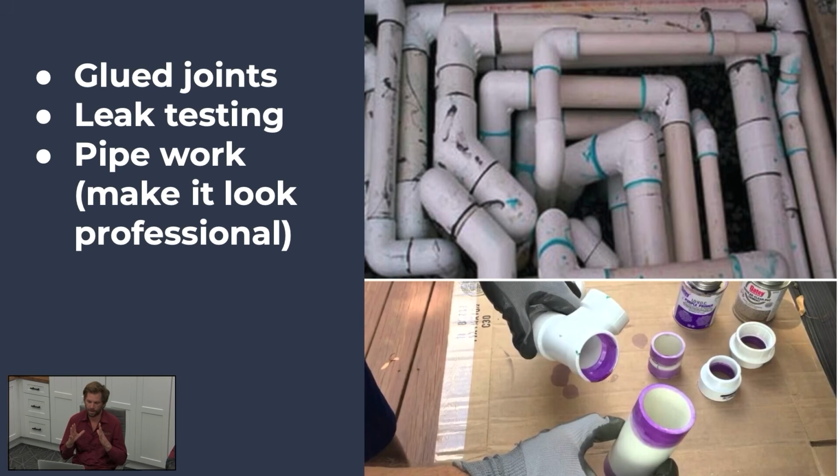What happens is that the chemical bond creates some pressure as it expands. And so what should be bonding the PVC to PVC is pushing it apart. The chemical reaction is pushing that bond apart as you go. So if you just make a really clean connection and leave it, typically it'll be leaking water there when it's time to turn on the water.